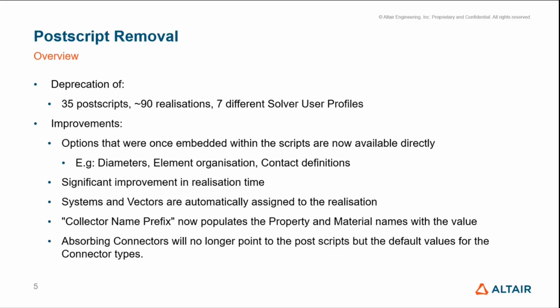What you should see on creation or loading of any historical deck, the model will still behave as it always will. It will still be pointing to the PostScripts for the moment. So if you import a legacy deck, you import a binary, nothing will change. Everything will work as you expect it to do. There will be no change from that perspective. Any connectors created new will then be using this new infrastructure. Any connectors being FE absorbed will now use this new infrastructure.